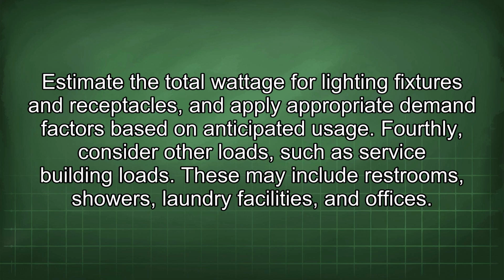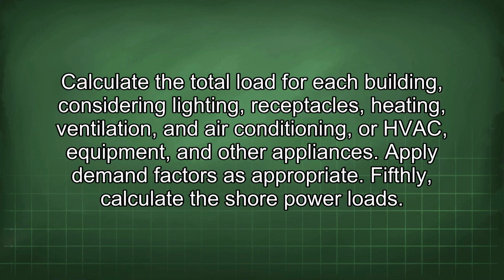Fourthly, consider other loads, such as service building loads. These may include restrooms, showers, laundry facilities, and offices. Calculate the total load for each building, considering lighting, receptacles, heating, ventilation, and air conditioning, or HVAC, equipment, and other appliances. Apply demand factors as appropriate.